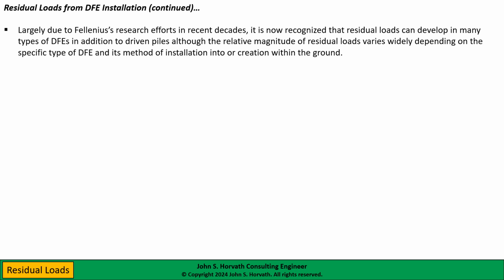Largely due to Fellenius's efforts in recent decades, we now recognize that residual loads can develop in many types of DFEs, in addition to driven piles. Although clearly the relative magnitude of residual loads varies widely depending on the specific type of DFE, and most importantly, how it's installed in the ground or created within the ground.